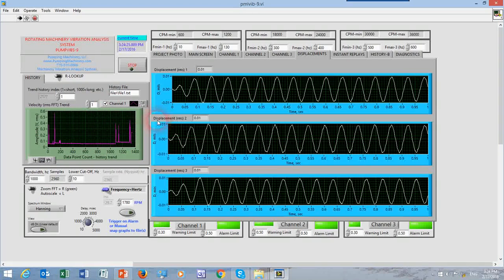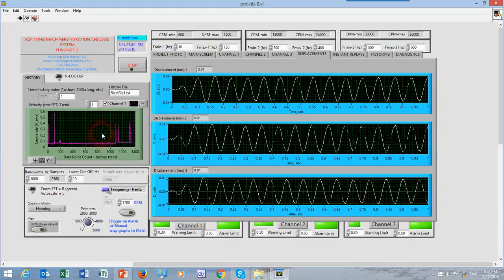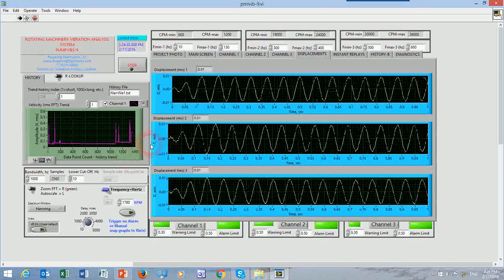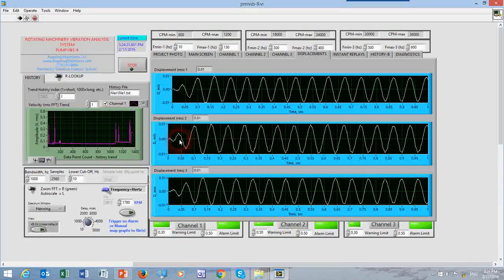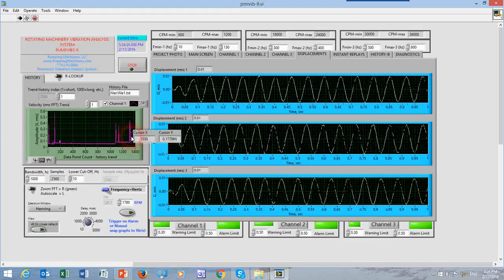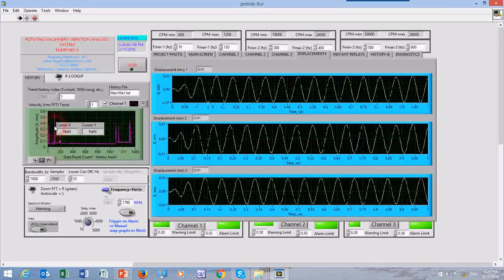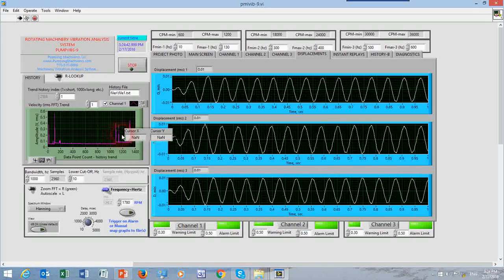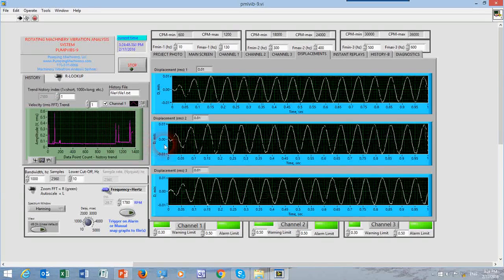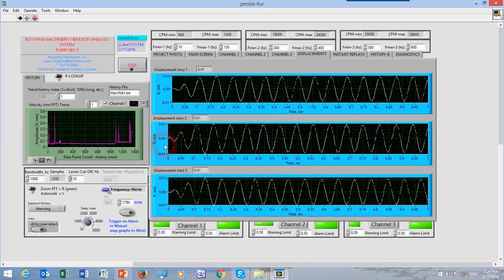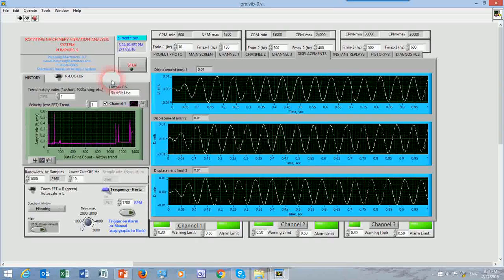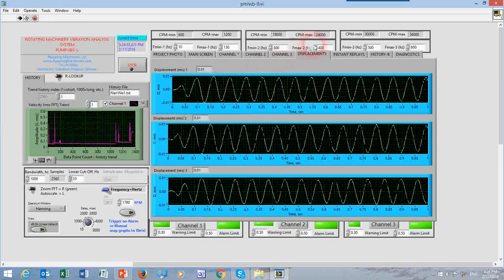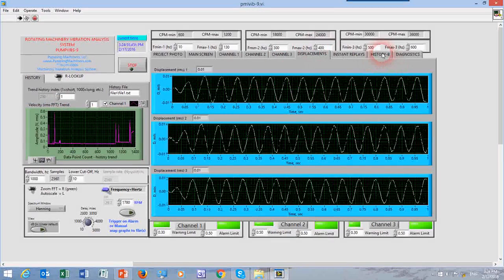Channel number 1 shows that we accumulated about 1,300 points in the last 10-15 minutes, with amplitude of vibrations reaching about 0.5, 0.6 inch per second. That happened a little bit earlier, and those spikes are where I was exciting the bearing housing to simulate a warning and alarm. If we want to get an expanded view of this history, we click History Big, so to speak.